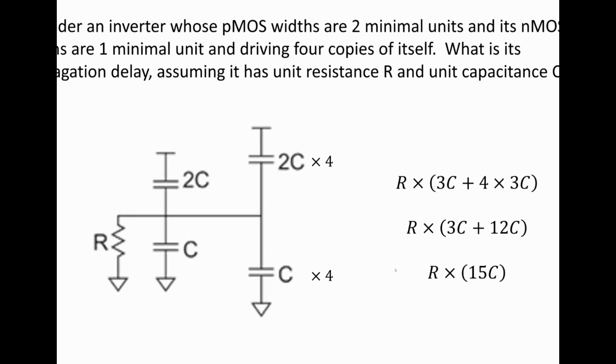Now this is okay. First of all, you might see this term called FO4. Every fabrication process has an FO4 delay. The FO4 is basically this: if you have a minimal size inverter driving 4 copies of itself, what is the delay? How fast is it? You can come up with that number in seconds for any process, and it's a metric that defines how fast a given fabrication process is. So yeah, that's FO4.